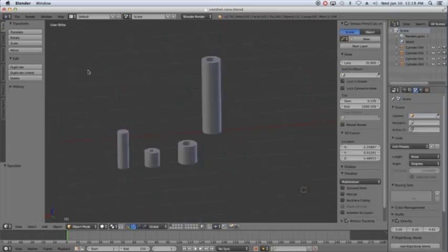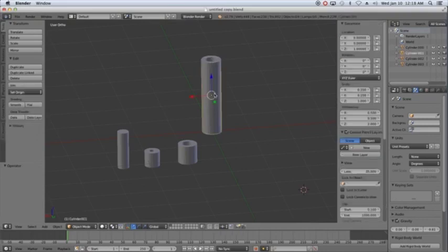Alright, here I have the components needed to make a prop holder. This one would be for a prop that goes over a 3mm shaft, and where the prop ends are 3mm. So I have this tube. It's 5mm in diameter, 2mm long, has a 3mm hole through it. This piece would be the center piece. It's 5mm in diameter, 5mm long, 3mm hole.